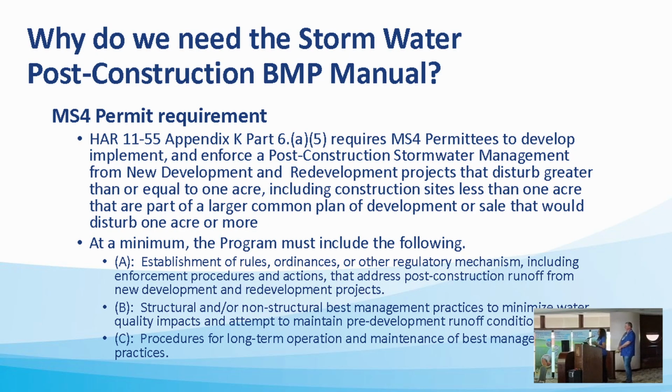So why do we need this manual? As the previous speakers have reiterated, there is an MS4 permit requirement. HAR 11-55, Appendix K, Part 6 has a requirement specifically related to post-construction BMPs, and it requires both the Oahu and Maui DOTs, who have MS4 permits, to develop, implement, and enforce a post-construction BMP program.